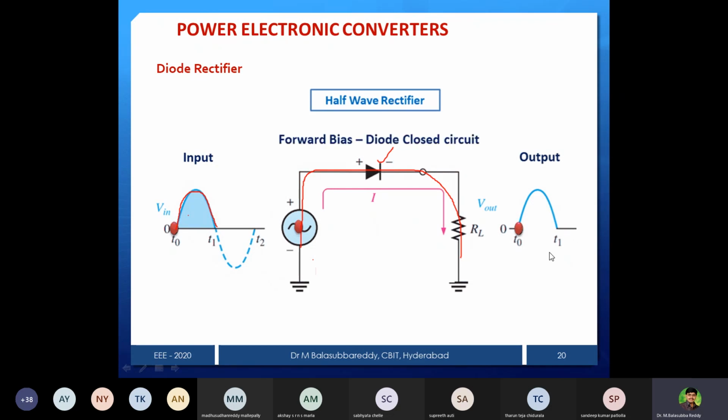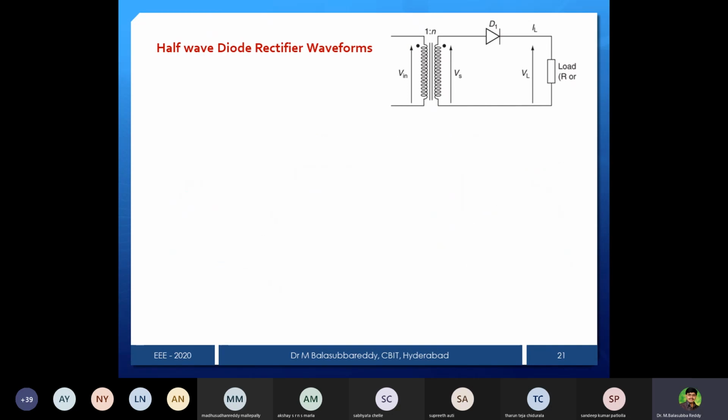If you want to use the bridge type of diodes, meaning many diodes, or a three-phase diode rectifier, all those things you can use. Whereas with thyristors, you get different voltages, with diodes, whatever output you are getting will be fixed. Now this is the half wave diode rectifier.